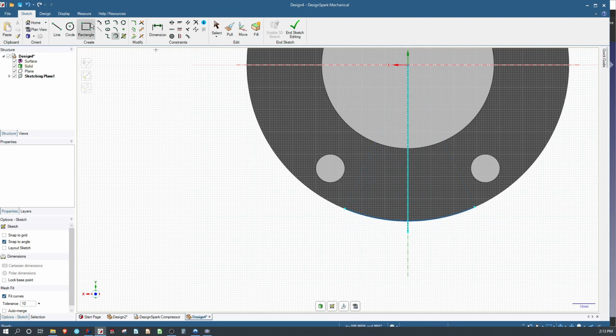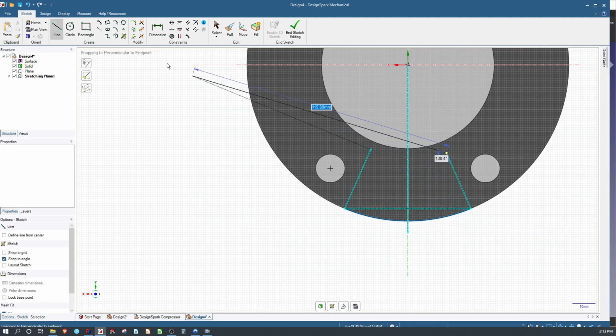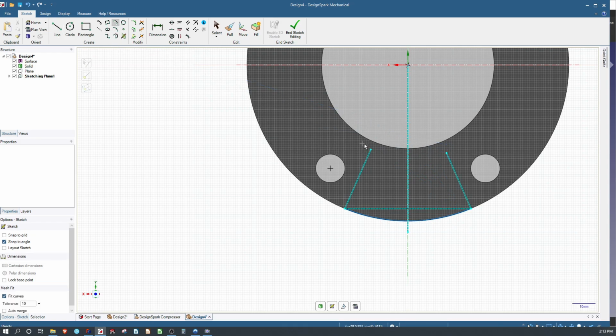So I've made a swept arc. We'll make a construction line for that. We'll go from point to point, and we'll set that to be horizontal. And then we'll go kind of eccentrically far. And then we'll have another swept arc. Actually, let's do a 3-point arc.